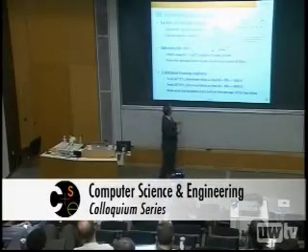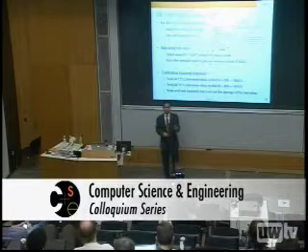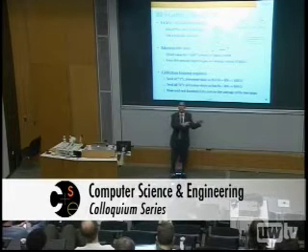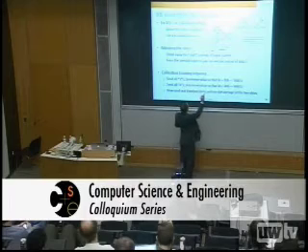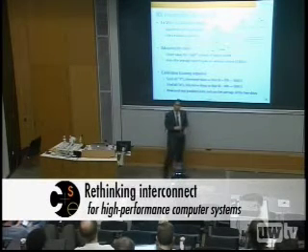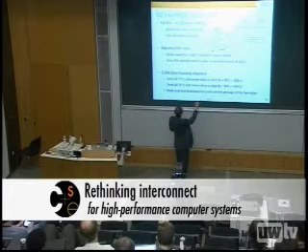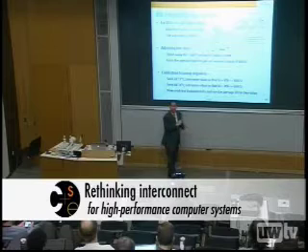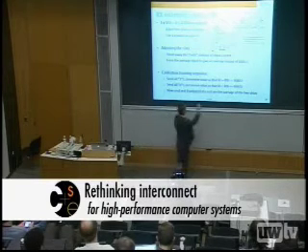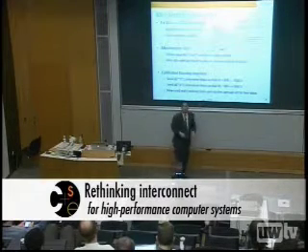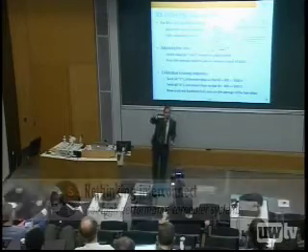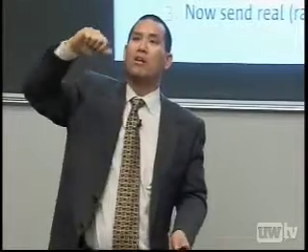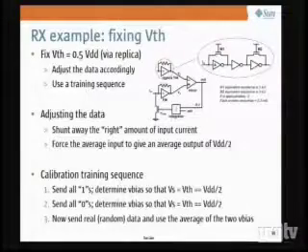We said, look, on the retraining sequence, let us first send a bunch of ones, right? All ones coming through. And so this is going to be a high value, okay? Now I'm going to use an integrator here and an adder and say that, well, I'm going to increase this bias current artificially to degrade a 1 value down to half. I'm going to force that 1 value down to the threshold point, okay? And I'm going to remember what that bias voltage was. So store that bias voltage that artificially dragged a 1 down to half.